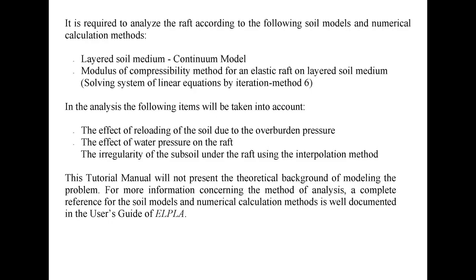In the analysis, the following items will be taken into account: the effect of reloading of the soil due to the overburden pressure, the effect of water pressure on the raft, the irregularity of subsoil under the raft using the interpolation method. This tutorial manual will not present the theoretical background of modeling the problem. For more information concerning the method of analysis, a complete reference for the soil models and numerical calculation method will be documented in the user's guide of ELPLA.